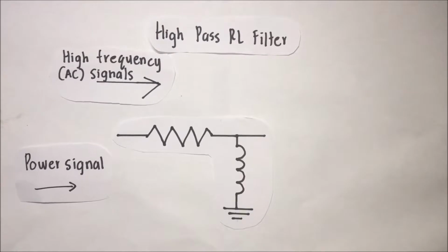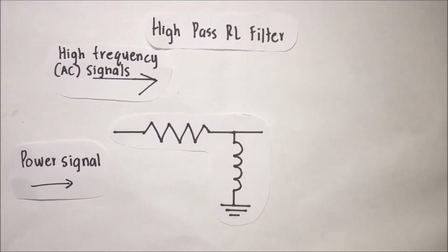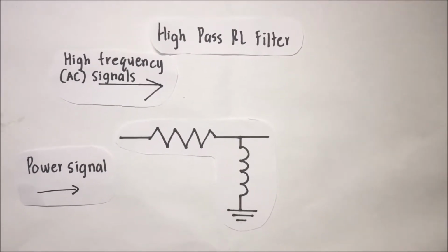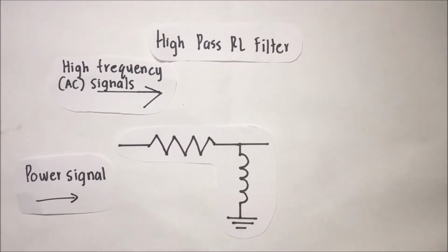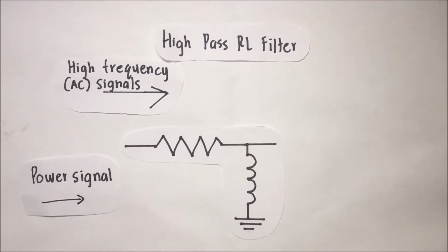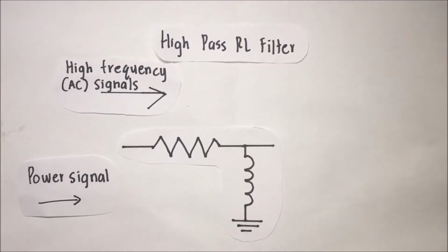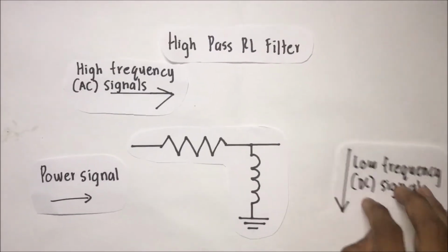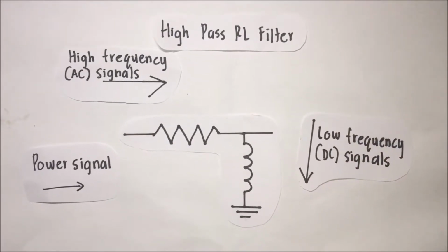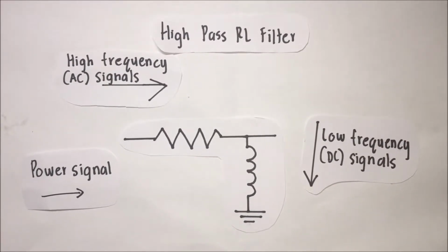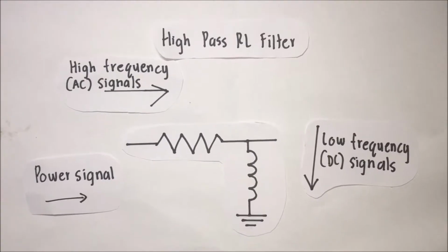An inductor, like a capacitor, is a reactive device. Inductors offer different resistance to signals of different frequencies input into them. Inductors pass low frequency signals with very little resistance, while offering great resistance to signals of high frequency. Thus, low frequency signals pass through very easily without any attenuation, and high frequency signals are either completely blocked or greatly attenuated as output.